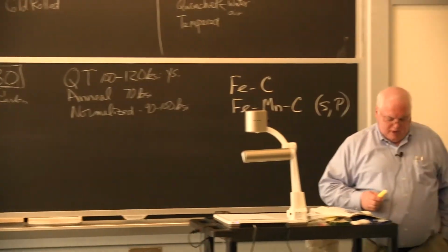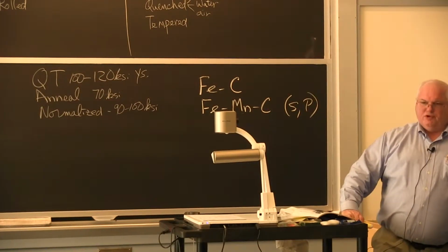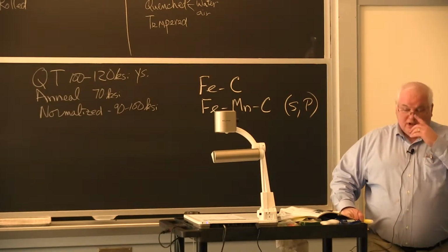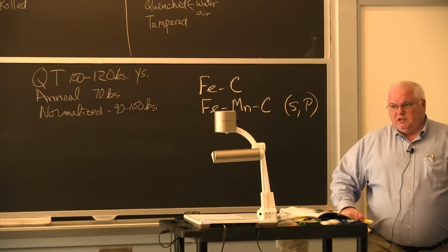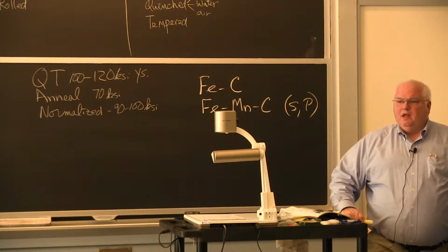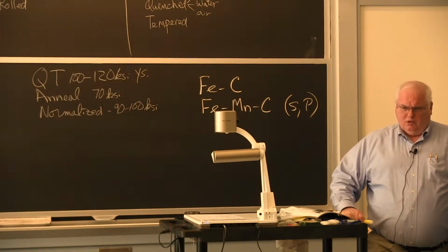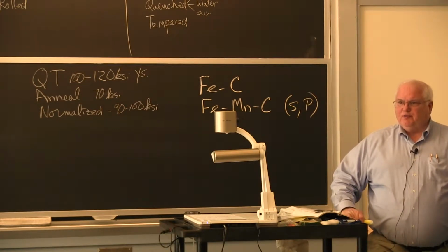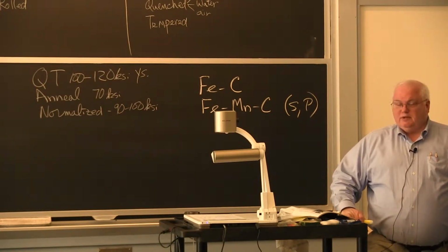And they still do. Manganese is not harmful. In fact, it's beneficial to strength and toughness and other things. It's relatively inexpensive, and it's really one of the only, it's the main use for manganese in the world, because on average steel has 0.5% to 1% manganese. If you got 1.5 billion tons, that's a market of several million tons of manganese.